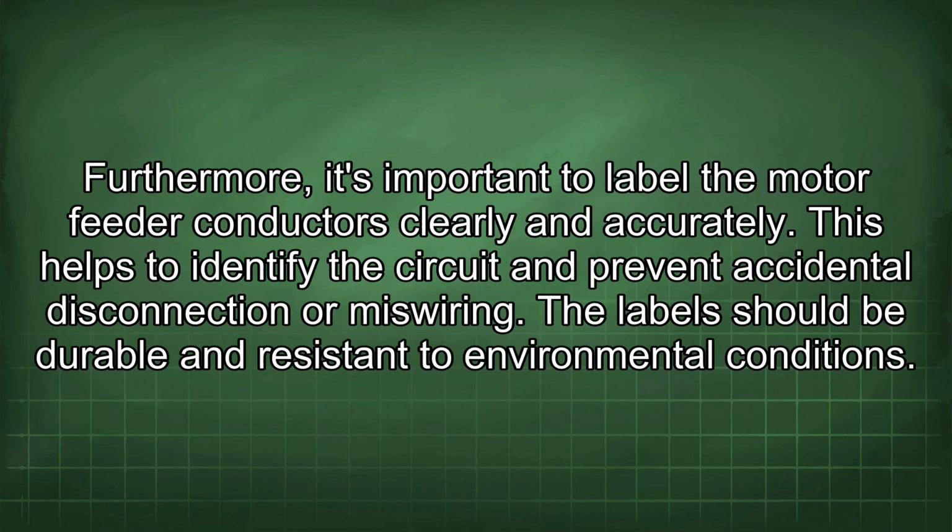Furthermore, it's important to label the motor feeder conductors clearly and accurately. This helps to identify the circuit and prevent accidental disconnection or miswiring. The labels should be durable and resistant to environmental conditions.